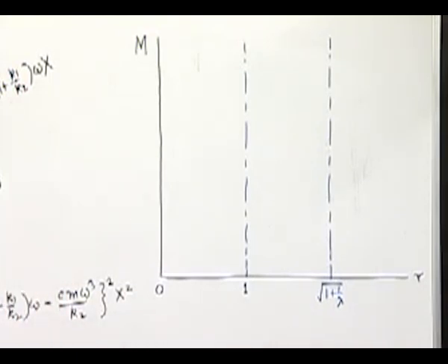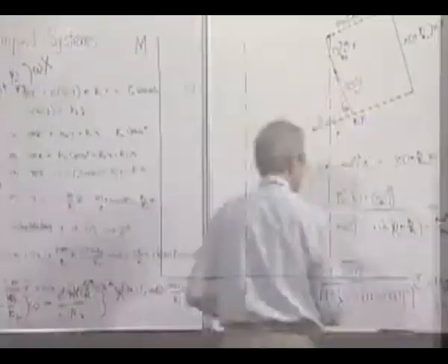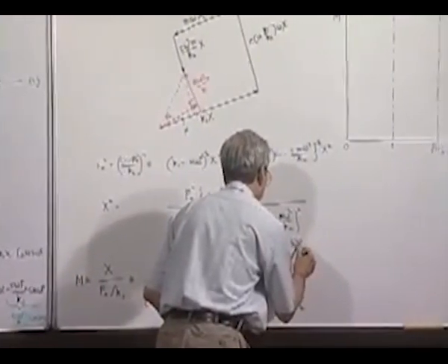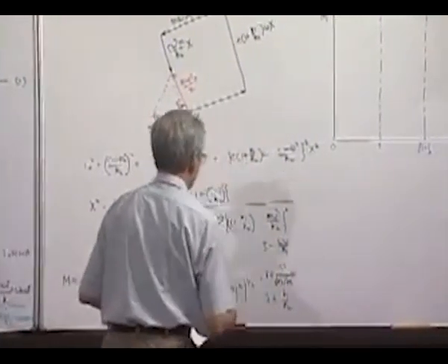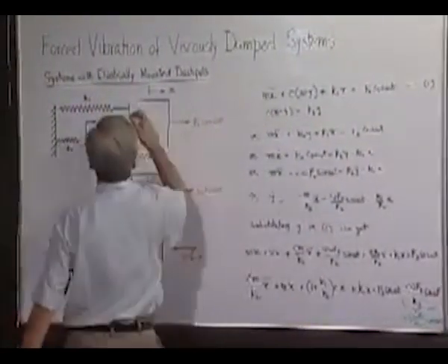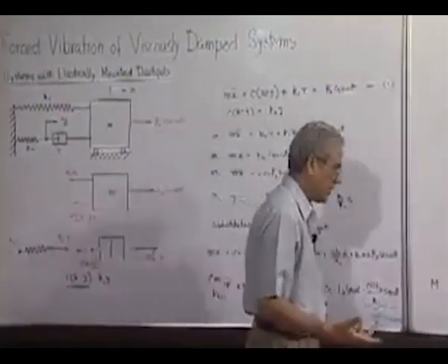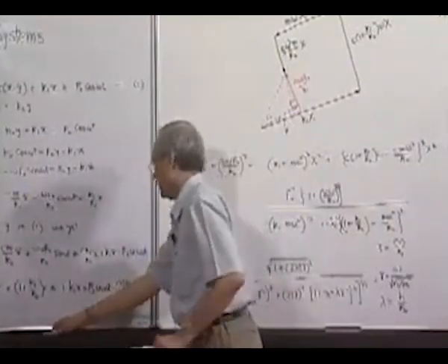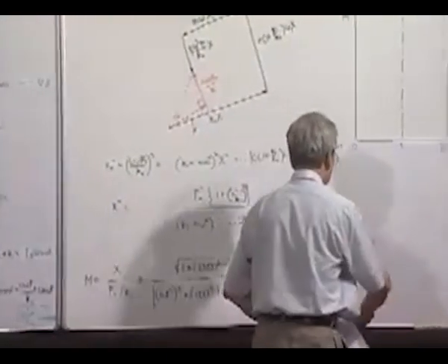now let us consider zeta is equal to 0. We will have some interesting results. Zeta is equal to 0 means, zeta of course is c omega by k1. When zeta is equal to 0, then obviously there is no contact or no connection. So it becomes a simple spring mass system, and its natural frequency is obviously square root of k1 by m, and the response will be as we have seen before.